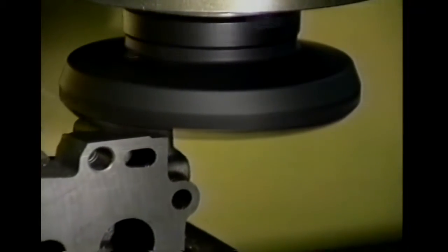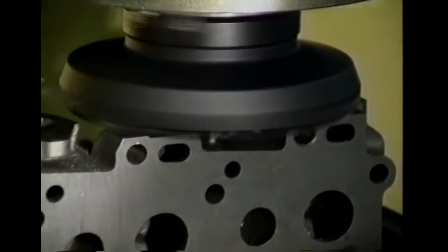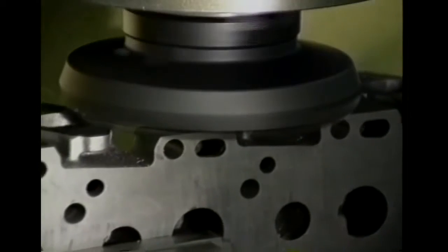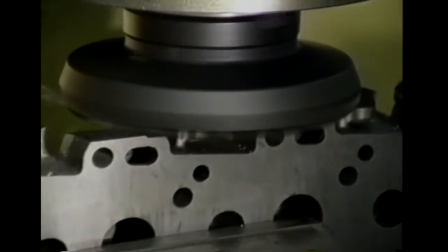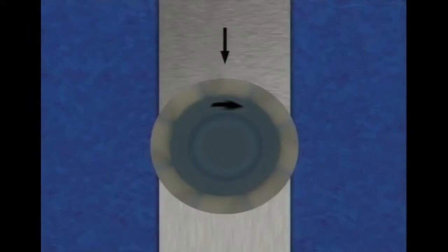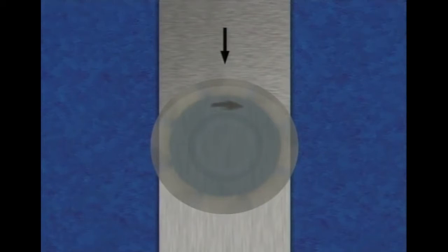For proper positioning, the face milling cutter's effective diameter should be about 1.5 times the width of the cut desired. This allows 1/4 to 1/3 of the cutter to overhang the edges of the workpiece, providing optimal chip formation. If the diameter of the face milling cutter is the same as or barely larger than the width of the workpiece, then the chips generated will be too thin at the entry and exit of the cut. This results in a buildup of heat and friction, which will reduce tool life.